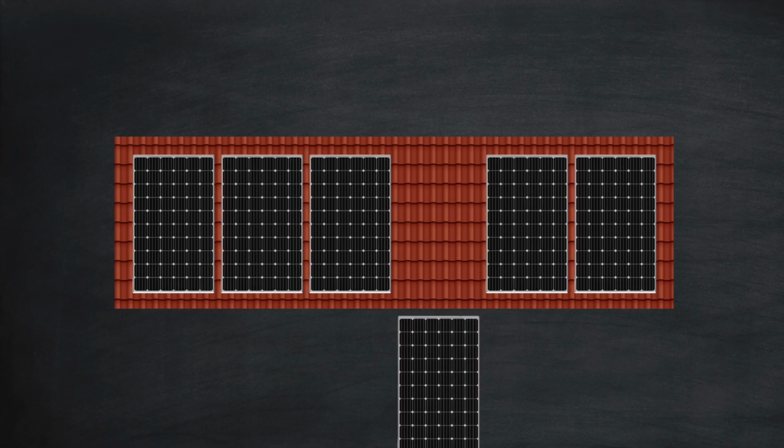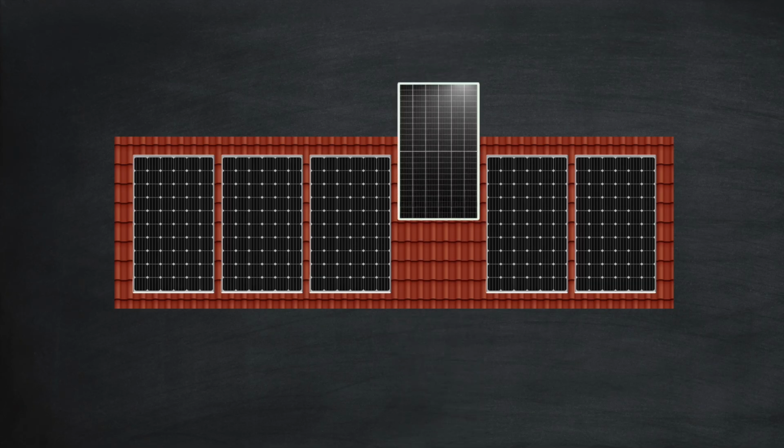In the unlikely event that you have a faulty panel, you will have to replace it. And if it's been some time since the installation of your panels, it may be that your panel make and model is no longer available. Your only recourse might be to replace the faulty panel with a near equivalent one. This isn't too much of an issue if you have optimizers or microinverters in place, but it could be a